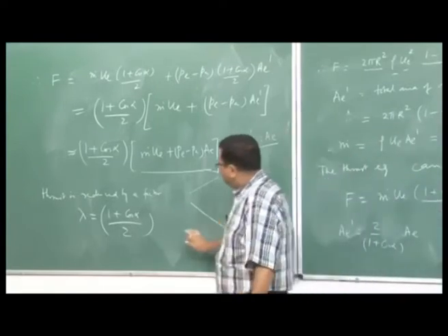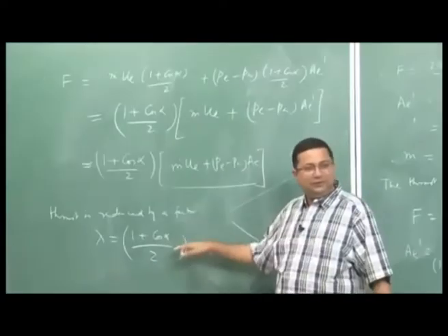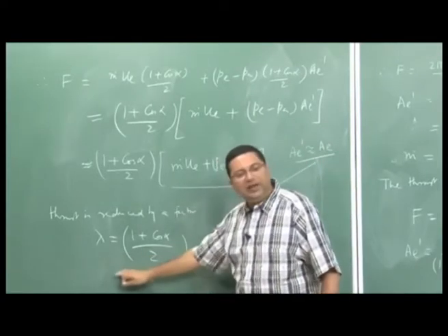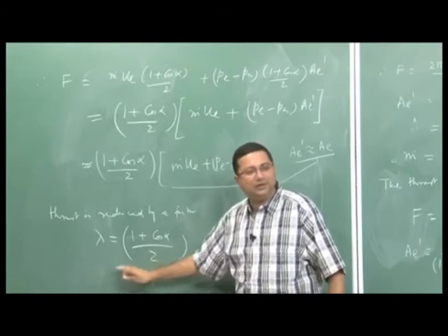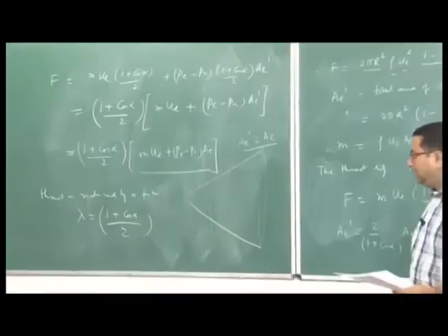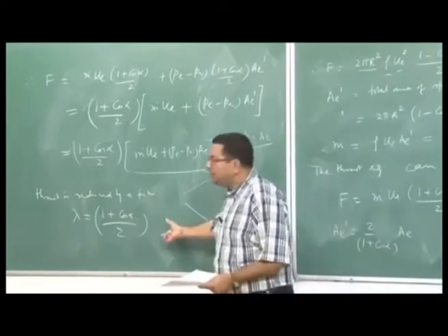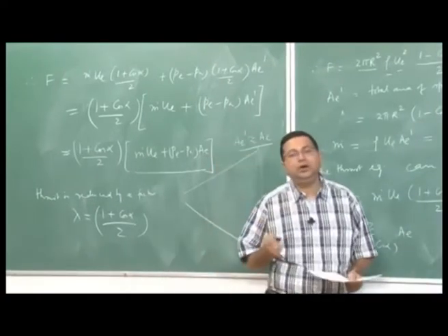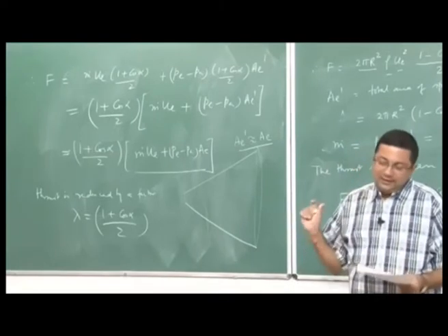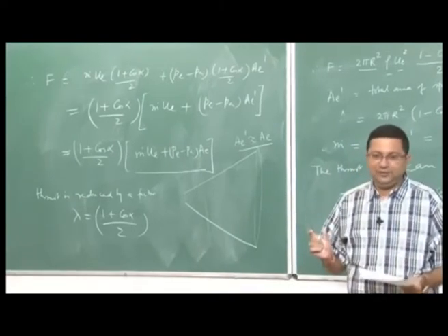Here we are considering a conical nozzle. So, the flow is coming at an angle and because of that angle variation there is a reduction in thrust, the factor that will reduce the thrust. So, primarily this reduction is because the flow is no longer one dimensional. Okay. But as you can see, this analysis is quite easy, very straightforward.